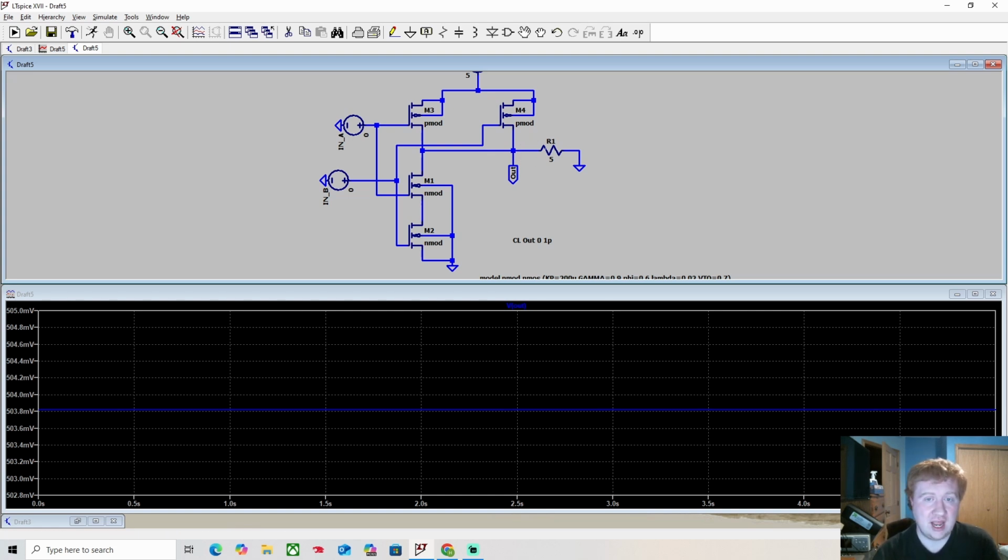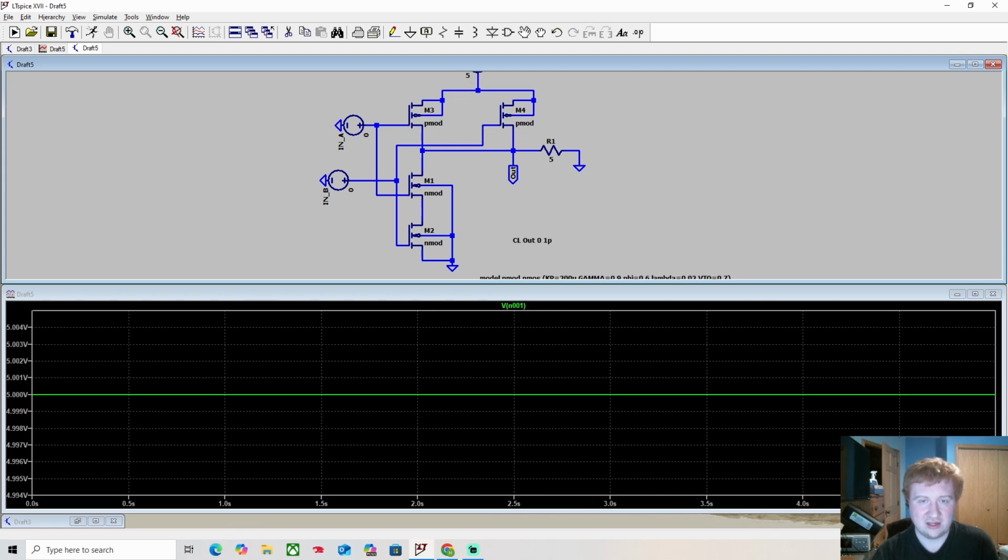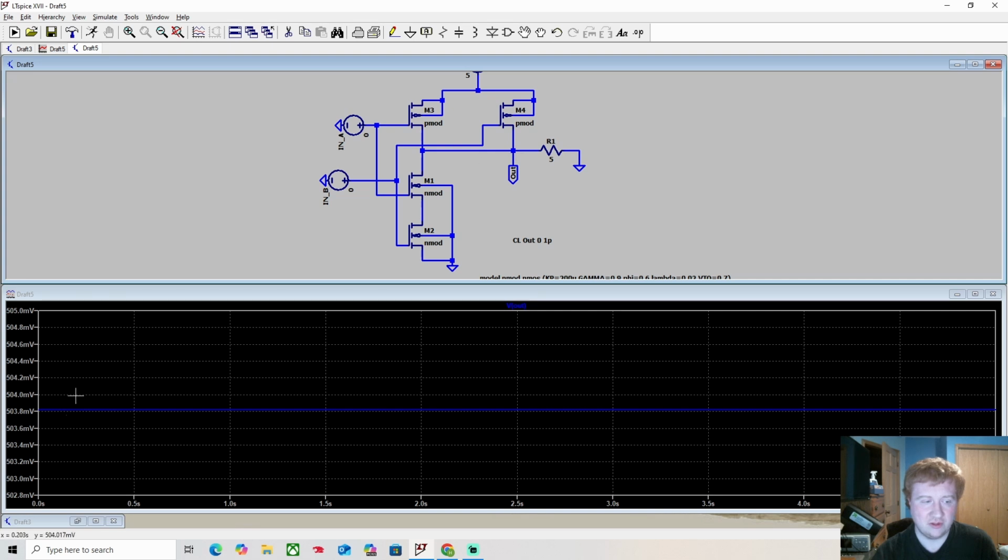You can't ask for too much current, otherwise it will mess up the output voltage, because down the line it'll change things. So that's why we're seeing only 500 millivolts. But still, it's technically functioning. It's just not 5 volts any longer.